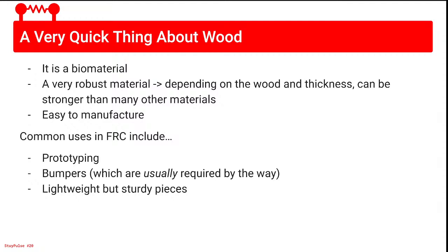Some common uses for wood in FRC: prototyping. If you have access to a laser cutter, it's really easy to cut, and Baltic birch is the most common one. It's used a lot in prototyping across the FRC community. And in fact, also bumpers, something that is usually required, except like 2015 apparently. You need to have bumpers to be able to play. There are specific requirements for it in the game manual, but you need to use plywood for it. So you have to have at least some wood around.